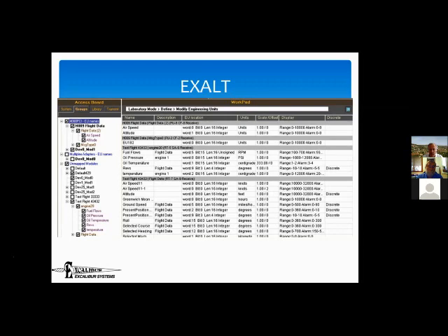Certainly on military planes, you're going to be seeing serial and Ethernet in addition to 1553. On civilian planes, AFDX, CAN bus, and ARINC 429 are really designed to work together, right? Because if you have a sensor that gives very little data, you really don't want to attach AFDX to that. CAN bus or ARINC is much more appropriate. On the other hand, if you've got the sensor on the end of a wingtip, you don't want to run a CAN bus from the end of an A380 all the way to the cockpit.